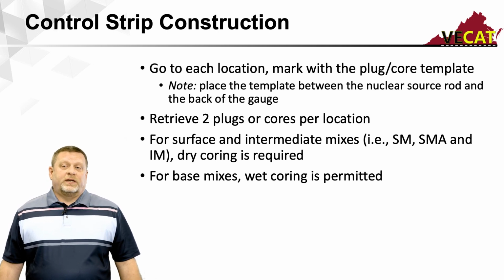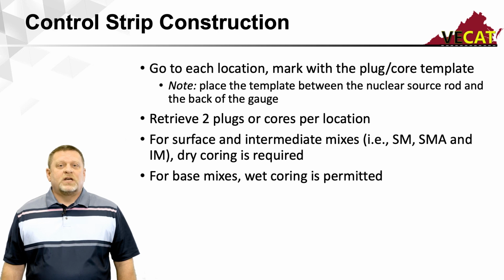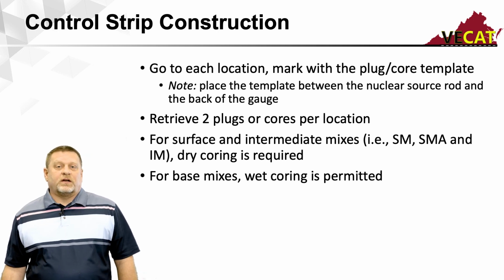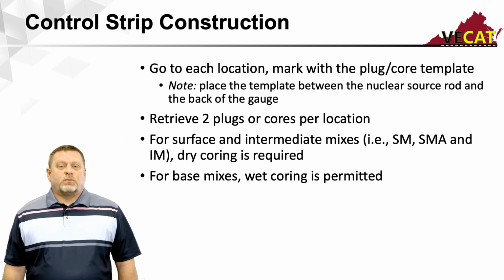You'll see this in some future pictures that I have that'll illustrate this. And we also have a nice core template that we're going to lay down on the ground that marks this so that the cores or plugs are the same size. We don't want them one place taking a 6-inch plug and the other place taking a 4. We have a standard size that we take, which is a 4x4 square, and we have a template we use to mark that.